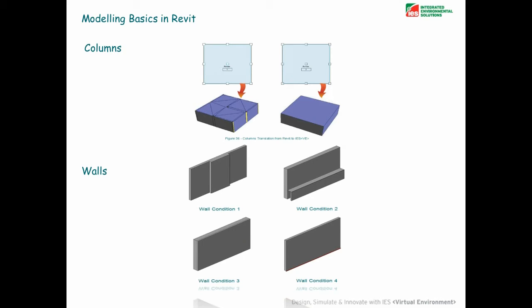If you've got anything else like sill levels or multiple room bounding layers to a wall, you need to uncheck these within Revit. What will happen otherwise is you'll probably have shading devices or surfaces coming through within your space. And it's a simple thing that you can do as you're going along building up your Revit model.